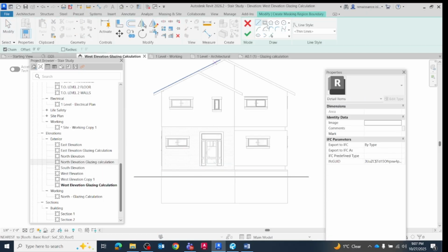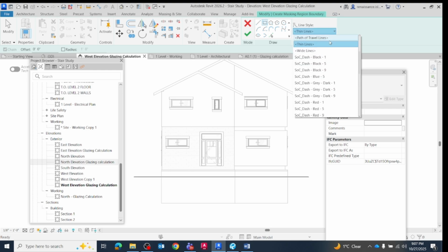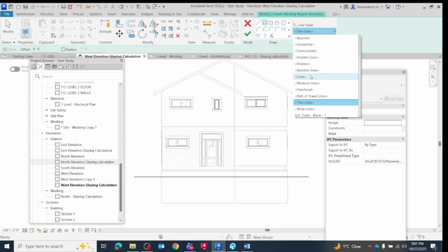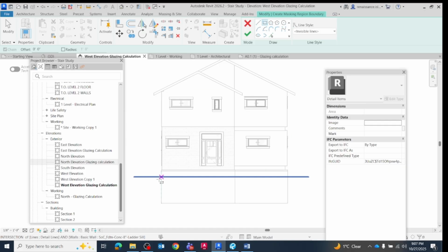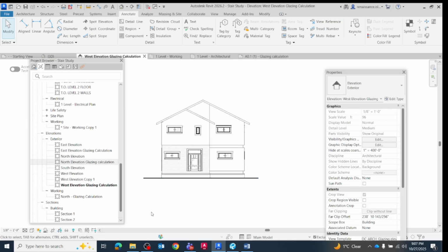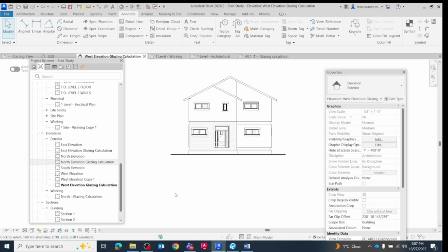So if you click on that, again, like that rectangle, and then what I will do is I'll pick the line, because if I just hide, it will show the outline. So I will choose the invisible line here, and now if you draw something over here and check, you will see that now my basement is hidden because I don't want to show that. I don't need to show that for my glazing calculation. My main focus would be from the grade level till the ceiling, right?